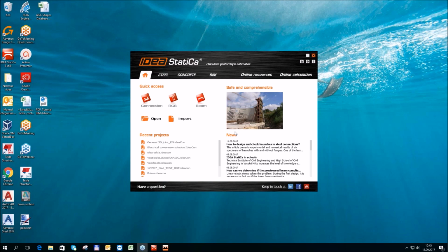But definitely it is considered in the ratio which you get. For instance, if I get the joint design resistance of 200% and I go to load effects and change everything to two times as high, I will see the results in the stress strain analysis.